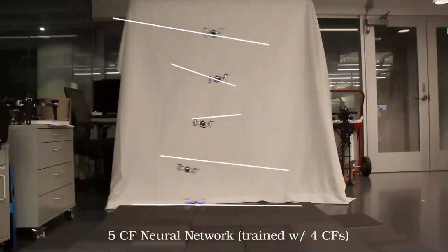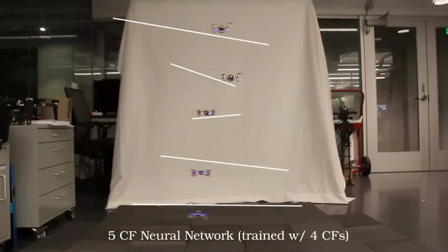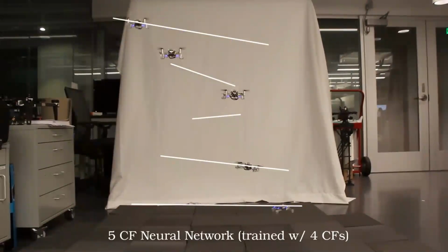And then if you apply the network, some of them still look bad, but that's actually because the motors cannot compensate anymore for the forces that are created. They're not powerful enough. But for the most part, the maximum or the worst case Z errors still reduced by a factor of 2 at least.